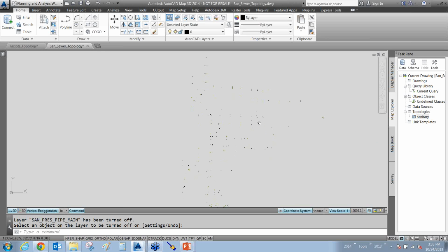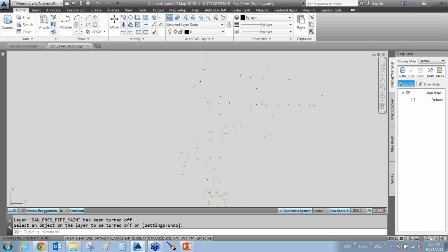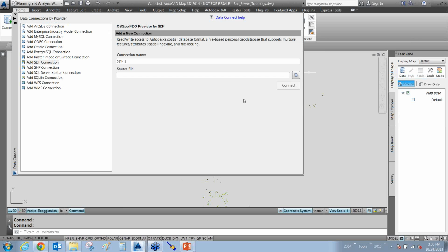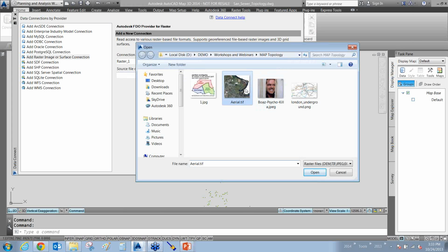What I would really like to do is, let's say that these are fire hydrants or sprinkler heads, and I know that for a fire hydrant I've got 250 foot of coverage around each one, because this is a non-residential area. I want to see if there's anywhere inside my city that it's not being covered. Now think about that for something like sprinkler heads. Those of you who do sprinkler coverages, do you draw circles around each one of them and see where the circles are and try to trim off the circles, et cetera? So this is the third use for topology. It's a really handy use.